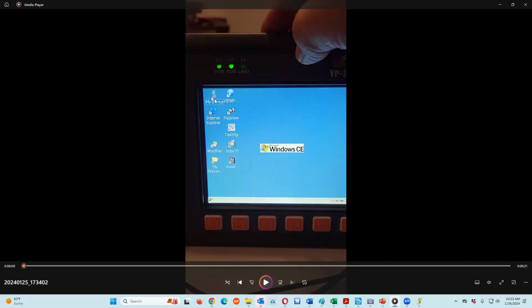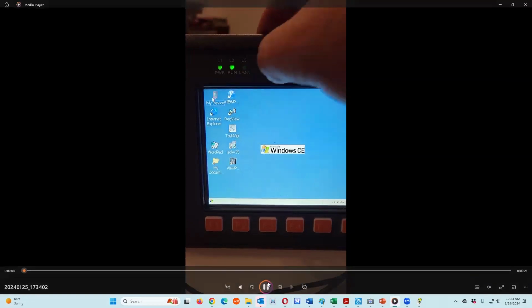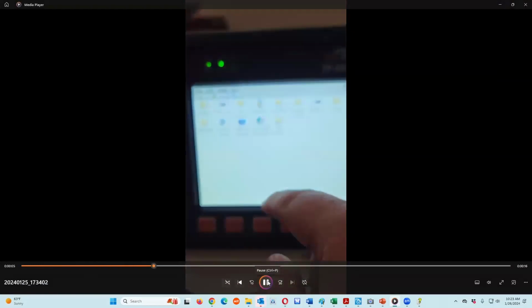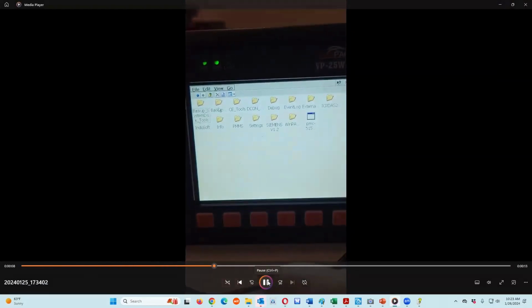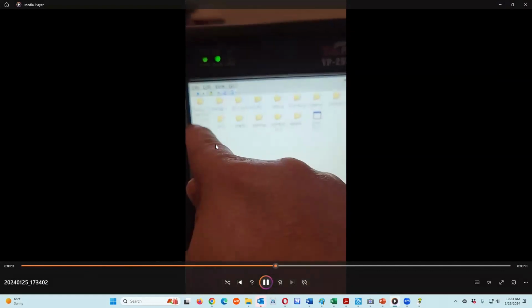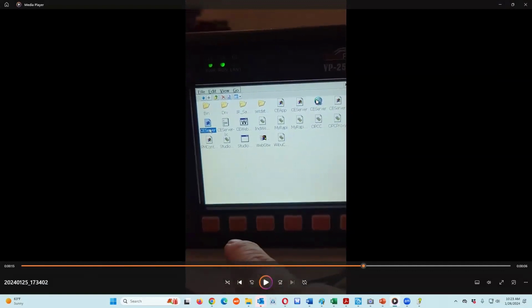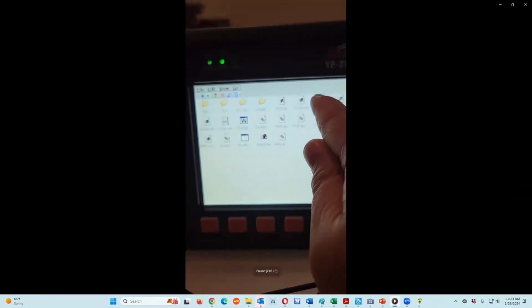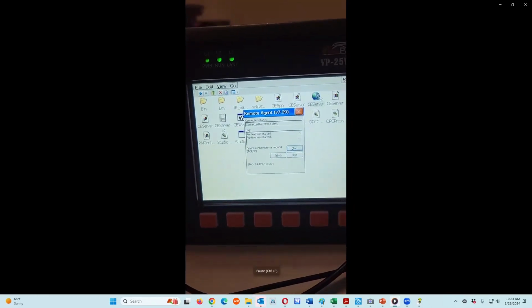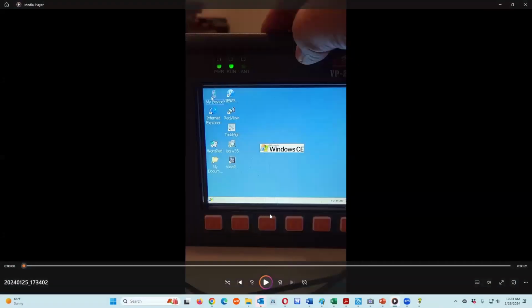Basically, you just open the file menu, and for us, we put it into the SD card. So you have to navigate to the SD card, and then for this, it's the InduSoft folder, and then you want to look for CE server, which is shown right here. Once you start that, the ViewPAC will be set up in the mode to receive a program. You can also auto start this if you want, but the first time you'd want to set it up this way, where it's set up to receive the program and receive the connection to the IWS.